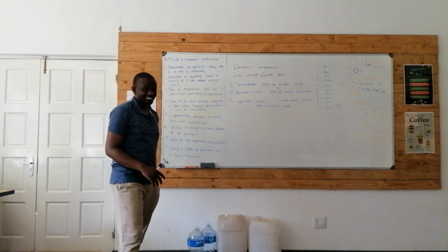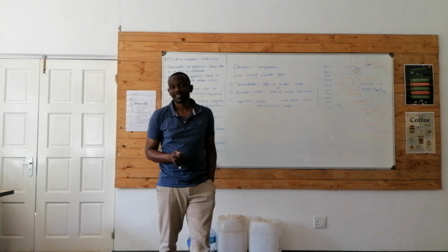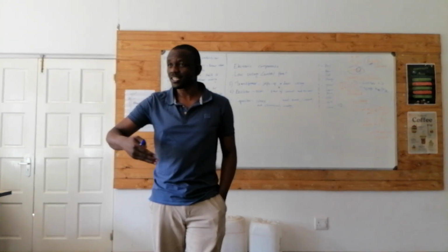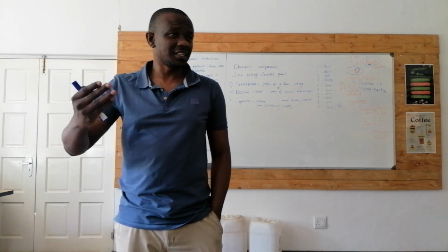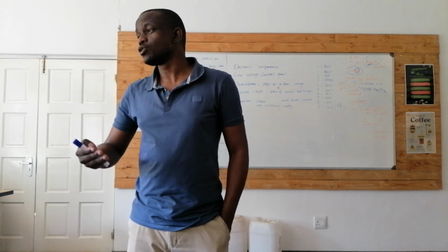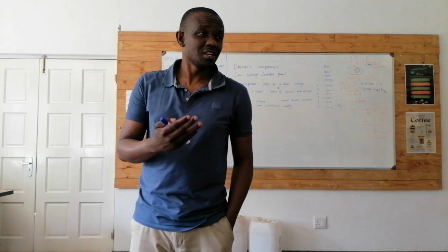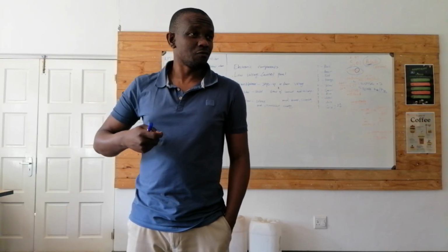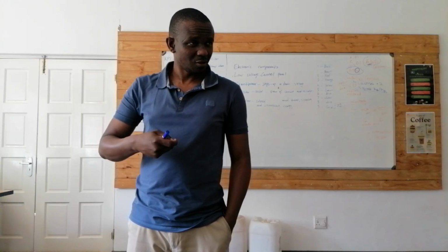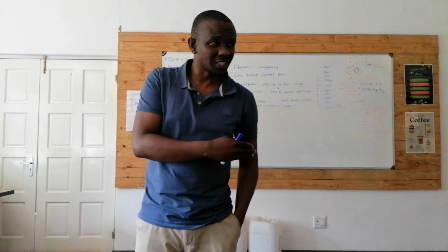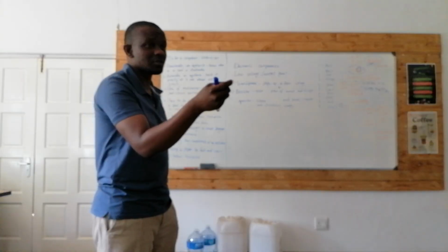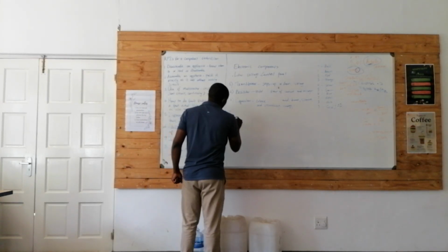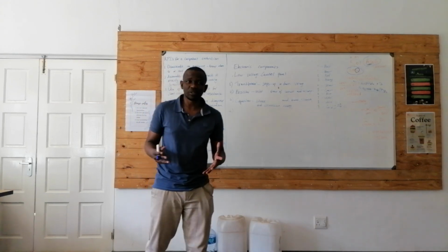3,000 volts through your veins will give you a humble pie, so you need to discharge it. Bigger motors that run elevators and other things, and single phase motors, use a capacitor. You can think of how much capacity that capacitor has. If you touch it without discharging it, you'll feel it nicely.